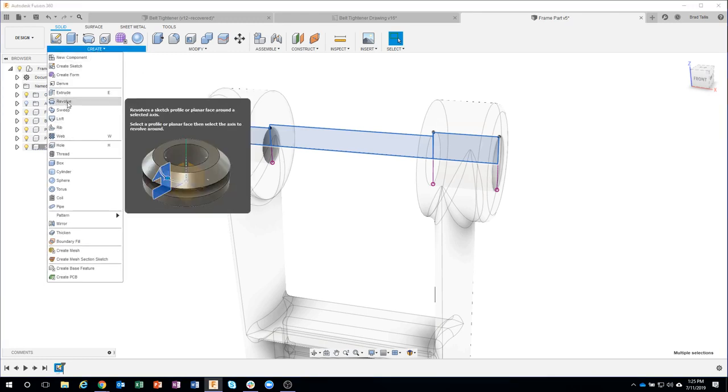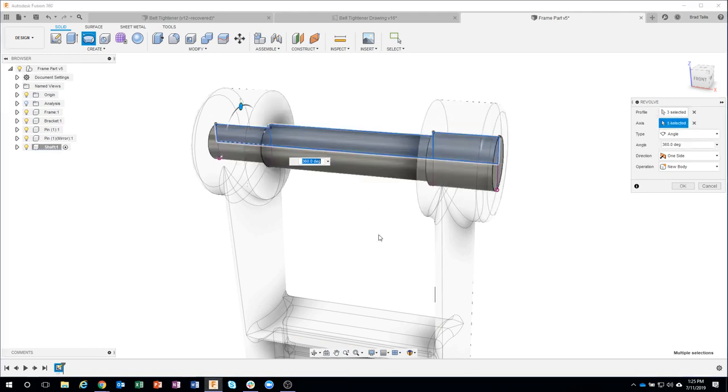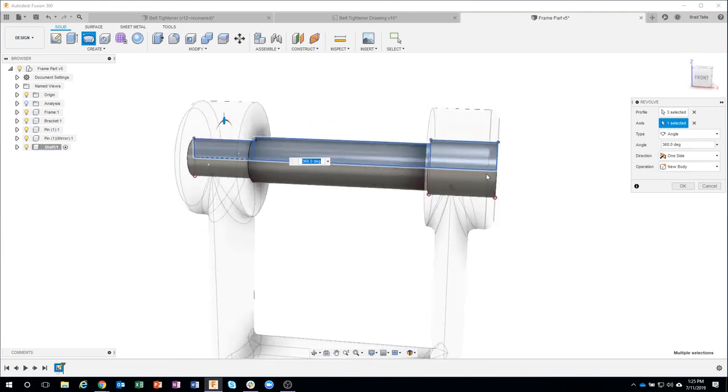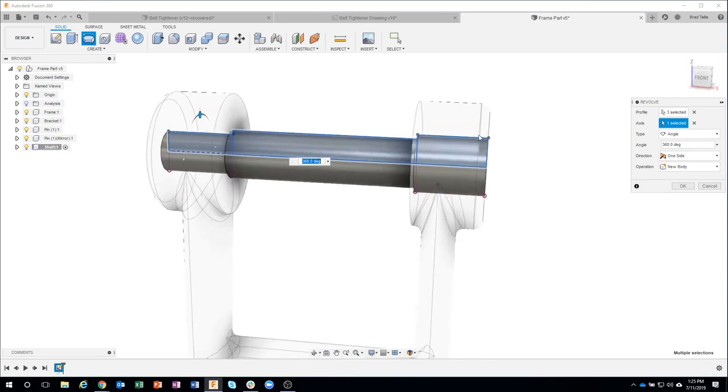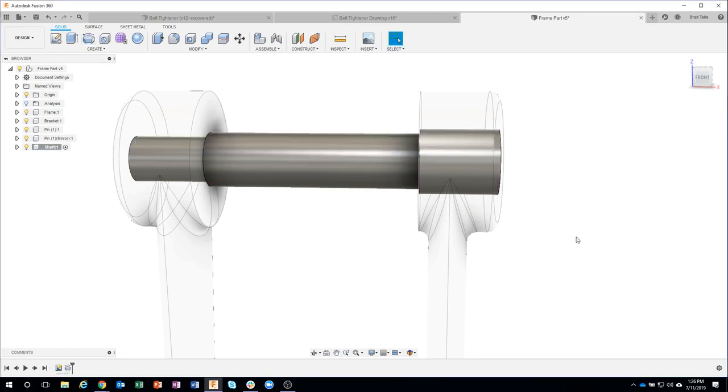Okay, we're going to create a revolution or a revolve. There's my profiles. 3 of them are selected. What's my axis? We're going to go around this center axis, and there's my 3D model. And again, it fits perfectly because we're using information from the 3D model. But this time, we projected it onto our sketch instead of doing machining type stuff like cuts and stuff like that. Okay.